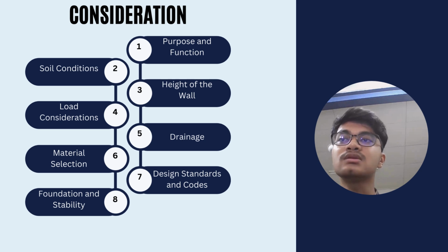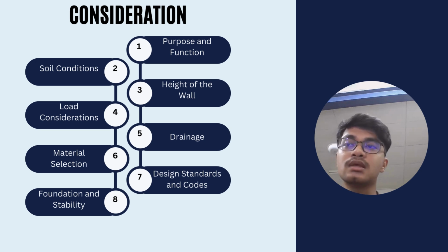And the last one, we need to consider the foundation and stability. Design a strong foundation to bear the wall load and prevent settlement. Consider the foundation depth, width, and type. So we need to enhance the stability of the retaining wall. So we need to consider these factors.